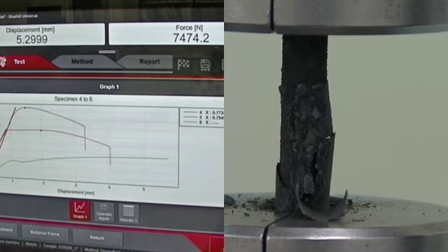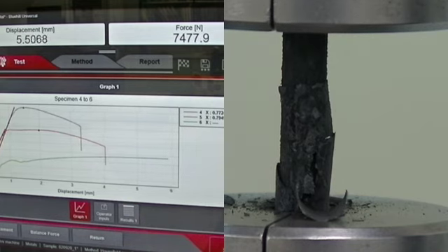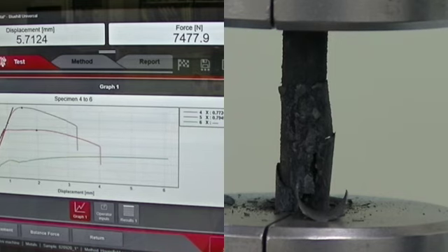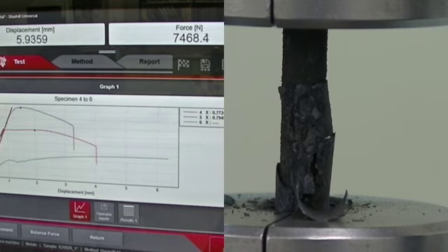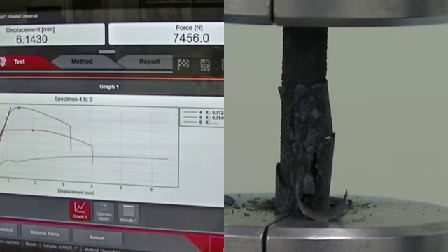It is worth pointing out for all the specimens, the maximum point is not the point of fracture. There's always some kind of extension before it does eventually fracture, and this is a warning sign, indicating the component or product is going to fail, offering an opportunity to intervene for possible replacement or fixes.